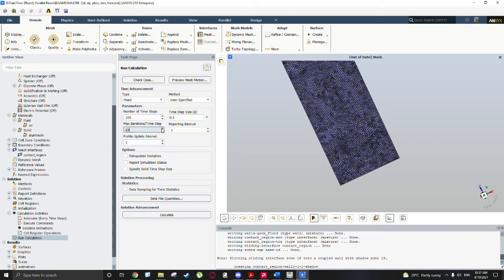Max iterations, usually up that a little bit. It'll use the maximum iterations to start with, and then once it starts achieving convergence, it'll automatically drop the iterations down lower. So don't be concerned that this is going to vastly increase your computational time. It will in the initial points of the simulation, but it'll automatically relax that depending on how fast it's achieving convergence.